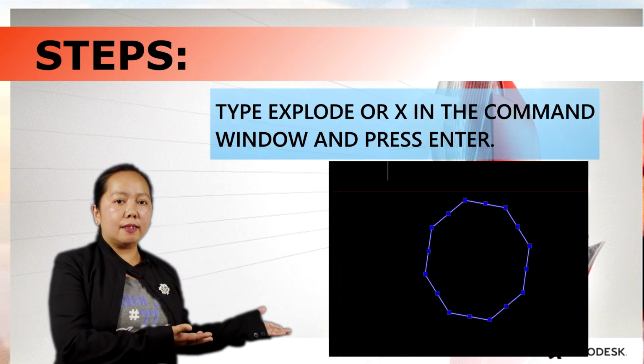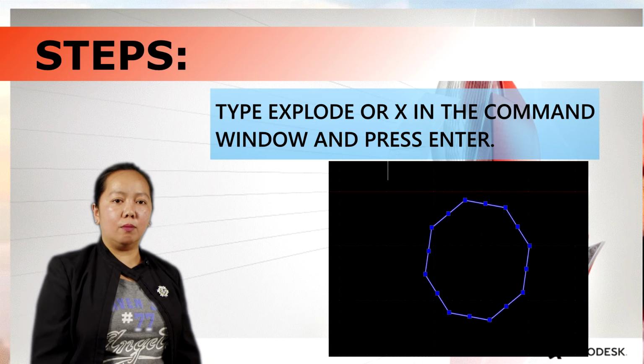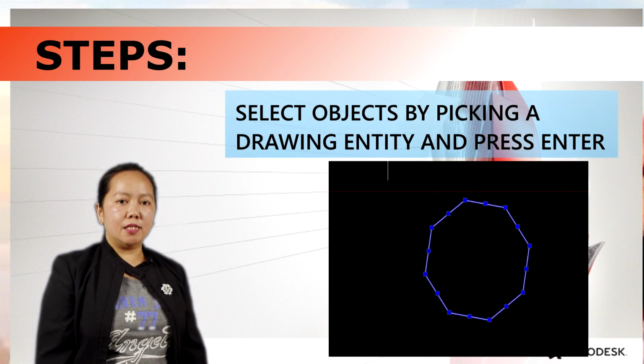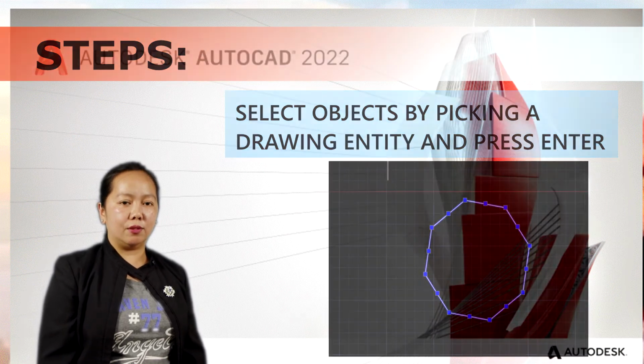Steps. Type explode or X in the command window and press enter. Select objects by picking a drawing entity and press enter.